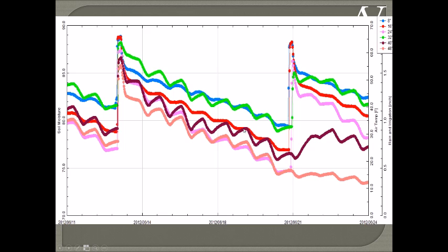So when you see this nighttime moisture increase, not just level off, but increase, that means moisture is coming from somewhere else. And generally what's happening is that this particular root system is actually really deep. It's somewhat unusual that these roots go down at least 7 or 8 feet. And they're tapping into moisture deeper than what we're measuring in this 4-foot probe. And when I see that, I realize that moisture is coming from below where we're measuring it.